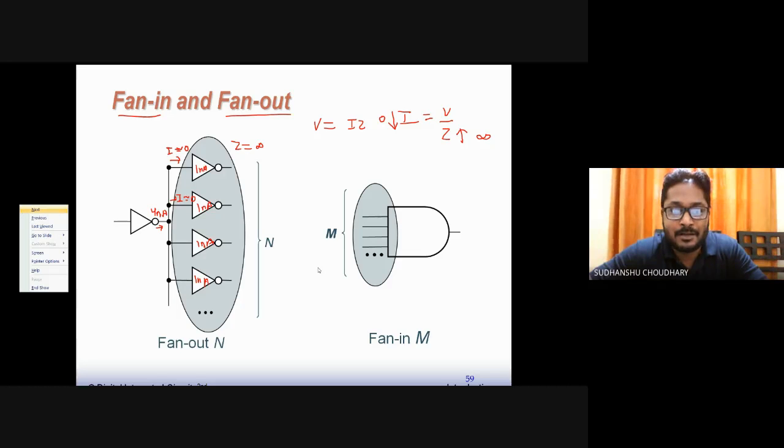So you have a connection of PMOS devices in series, and PMOS are already slow, so the resistance in series will make them even slower, and then the propagation delays at the output can be affected. So the overall circuit will become slow. That is why there is a maximum limit on the number of inputs that a gate can have. That is, fan in has some limitation, but for fan out, it is always desirable to have a very high fan out. Infinite is very good. That is the best situation.